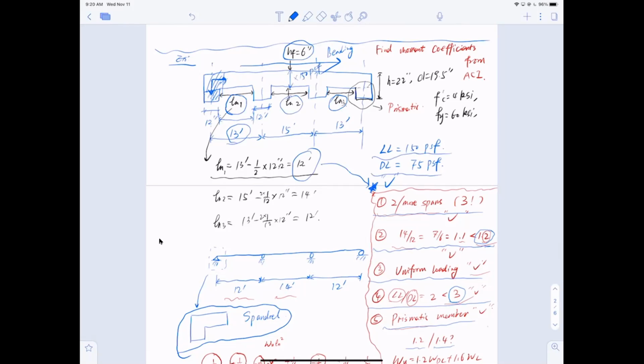If we say the beam has to be considered, instead of 6 inches, you add the beam height as well. For example, I don't know, this is 22. So use 22 multiplied by 150 pounds per cubic foot. Okay, so just use different heights to multiply the density, and you get the self-weight. You consider the self-weight. All right, so that's how you consider the dead load.